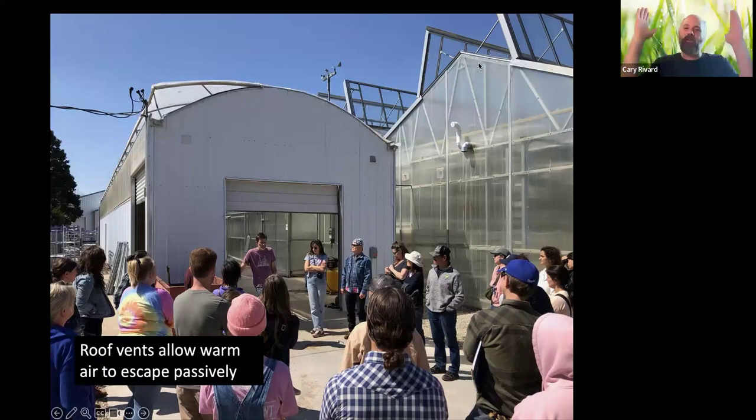And you can see it opens all the way at the top like a cathedral. What that does is it allows all that hot air to escape. It's really remarkable working in greenhouses that have roof vents because they're passive. Once this roof vent opens, all the other ventilation fans turn off because you don't want to draw air in through the roof. You just want it to let the hot air out, right?